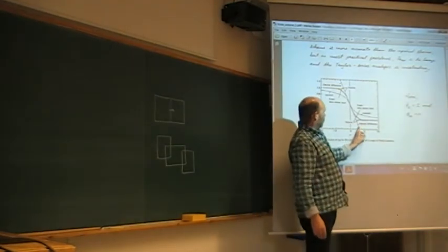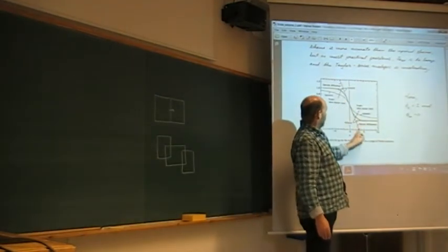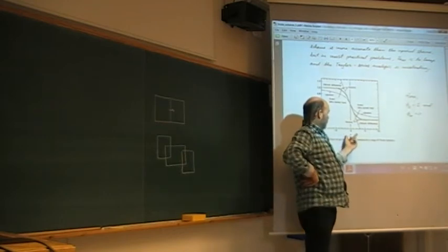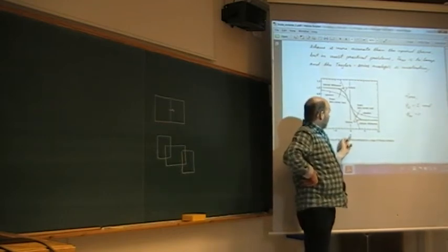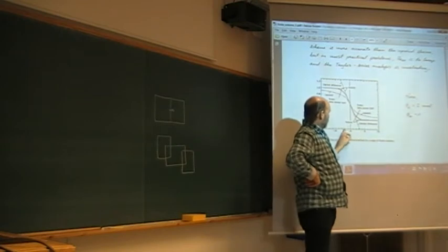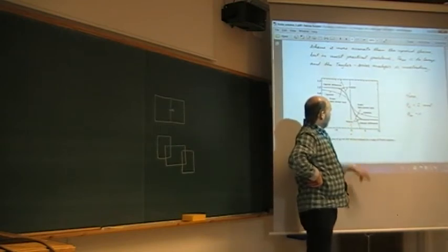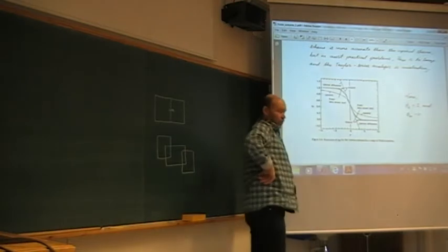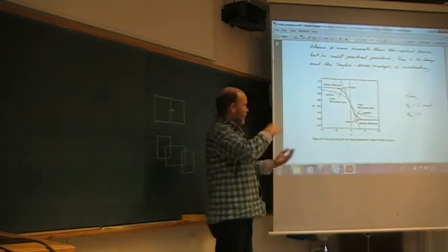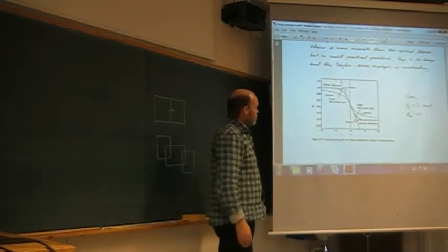The central difference will be a straight line, varying linearly with the Peclet number. But go outside plus minus 2 and you are really in trouble. Then it blows up, starts oscillating, quite unphysical behavior.